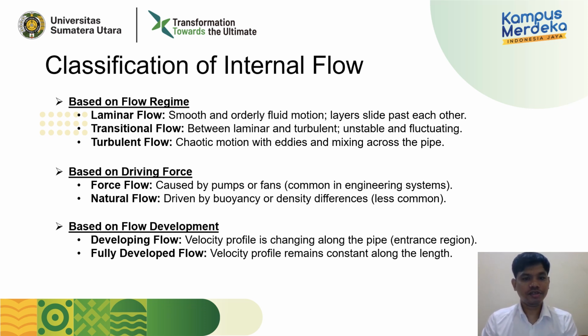The second classification of internal flow is based on driving force. The first one is forced flow, caused by pumps or fans. It is common in engineering systems. And the second one is natural flow, driven by buoyancy or density difference. Like gravity force, for example in a hydro turbine system, you need to flow the water from the dam into the turbine.